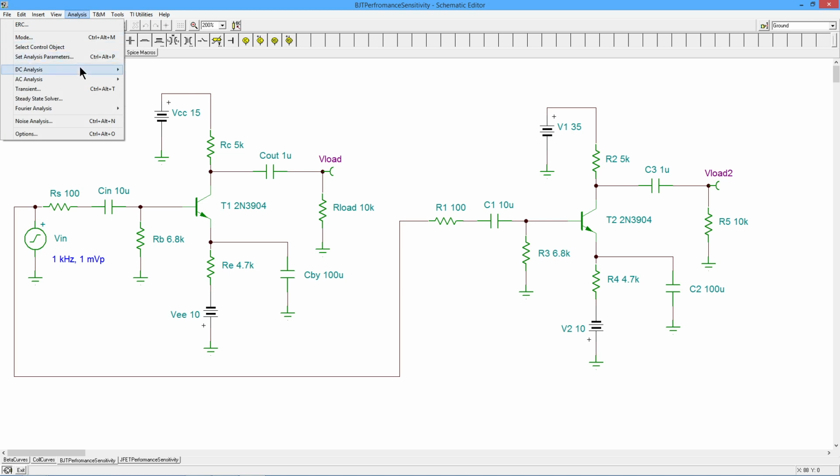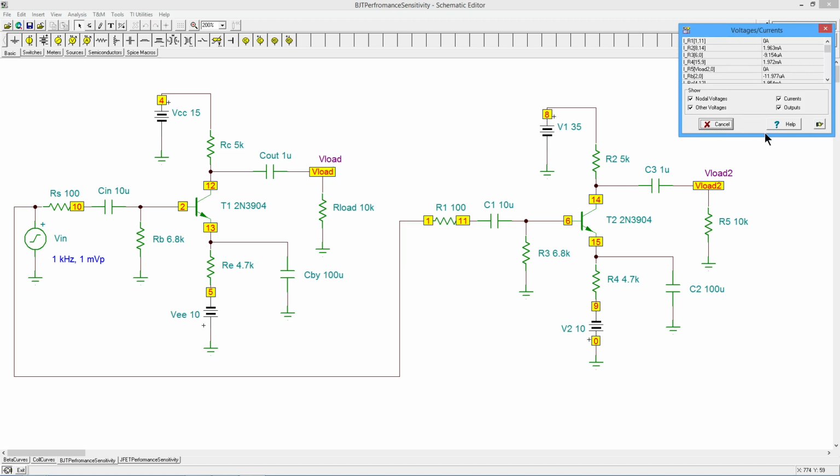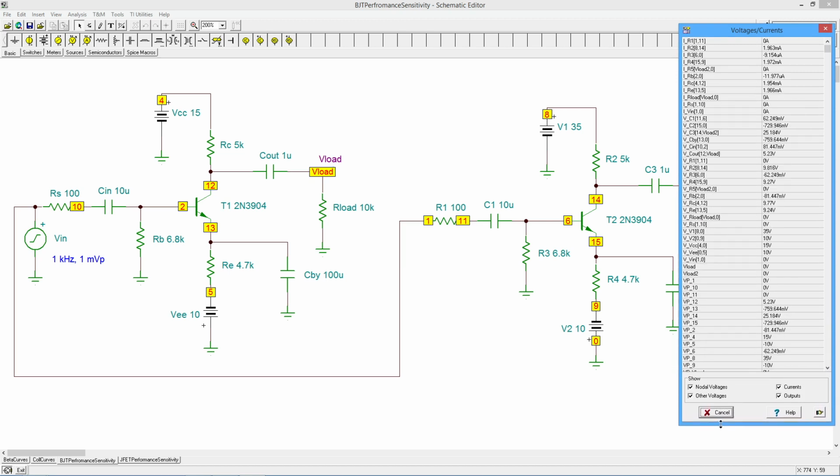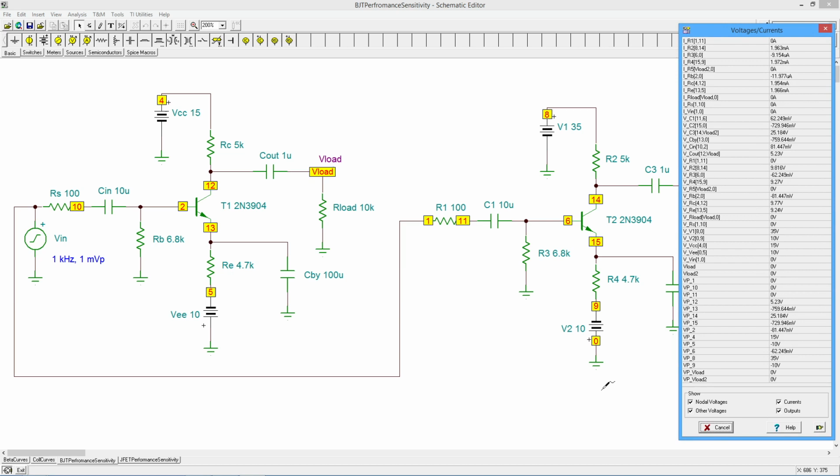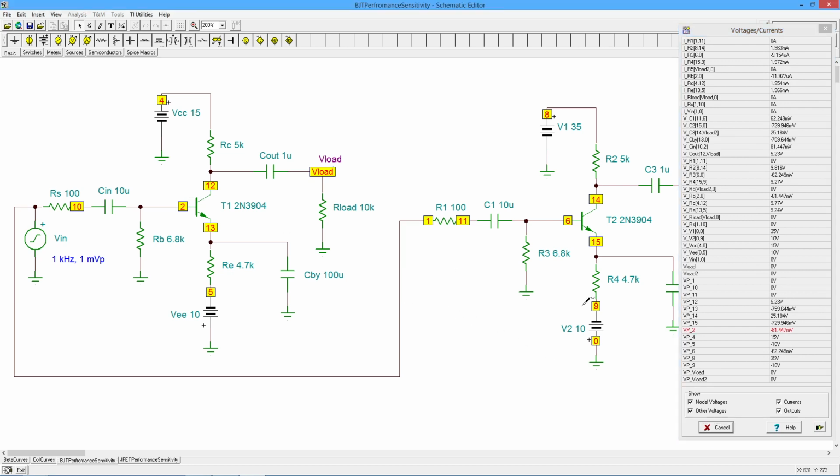But virtually everything else is the same between these two circuits. We can do a real quick analysis here on the DC end and just start poking around and looking at points and see what we actually get. So like I said, bases should be pretty close to 0. This one's coming in at negative 81 millivolts. This base is coming in at negative 62 millivolts. That's pretty small, you've got tens of millivolts. This emitter is coming in at just about negative 730 millivolts, and this one is about negative 760 millivolts.